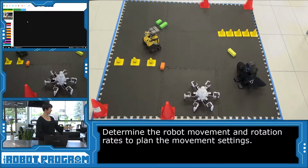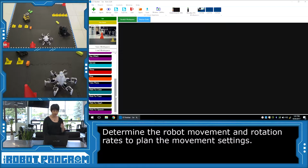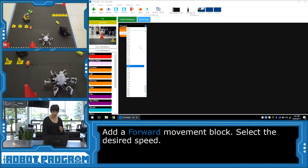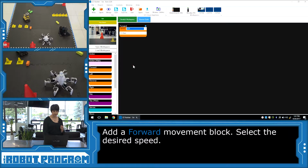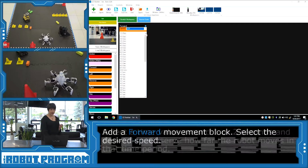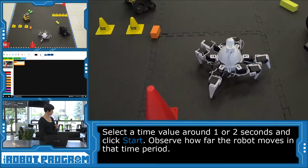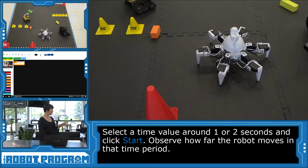So I've placed Six in a nice clear area where he's got lots of room to move. And the first thing I'm going to do is just understand how long it takes Six to move and how much room he needs. So I'm going to go into Forward. I want Six to go through this obstacle course fairly quickly, so I'm going to go around 225. It's almost his top speed. Okay, let's just change the time to 2 seconds. When I click Start, we're going to see how far he can move in 2 seconds. Okay, so about half of one of my blocks, maybe a little bit less.